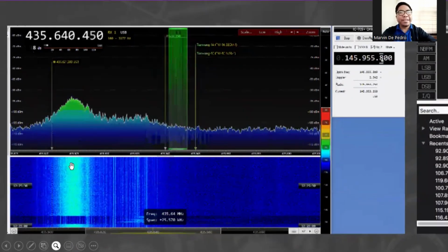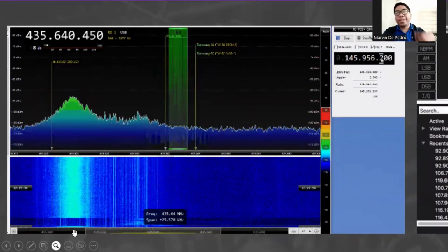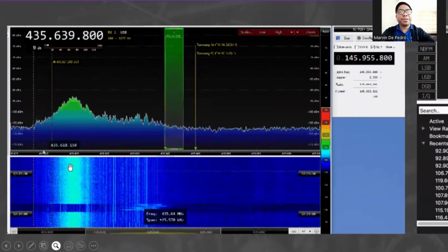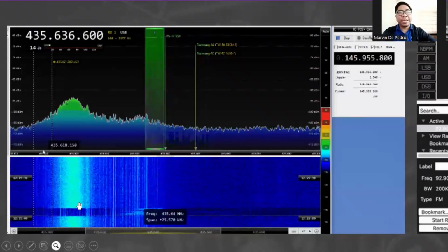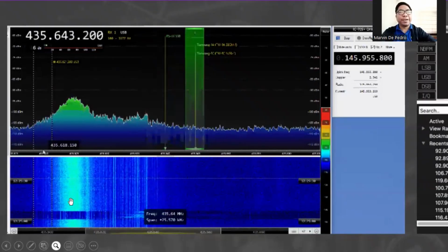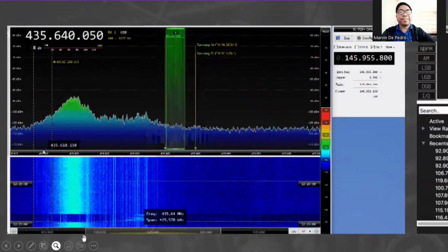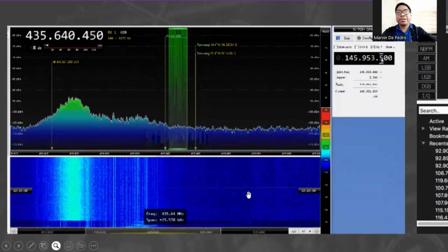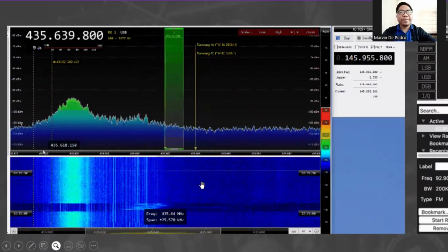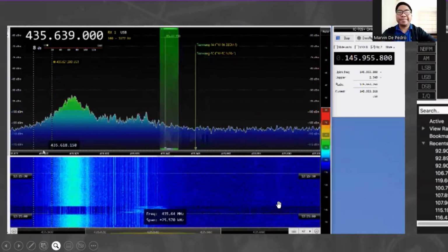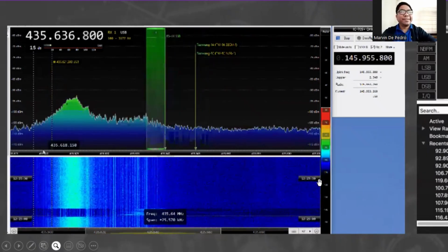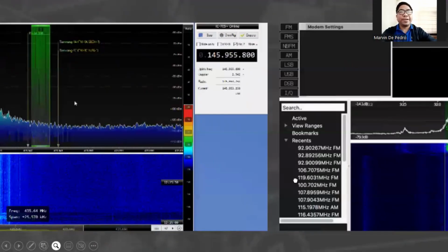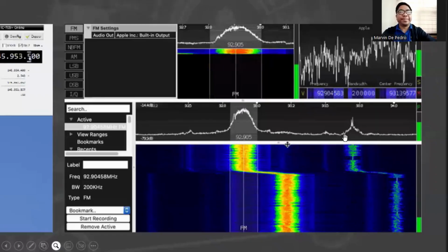Okay, and here using the waterfall display or the spectrogram, waterfall type of spectrogram, you can see here that this portion actually has intelligence or a message. It contains some data, while the rest are somewhat like just noise or some irrelevant signals. Okay, so with that, it's easier to tune into a certain wireless communication system.